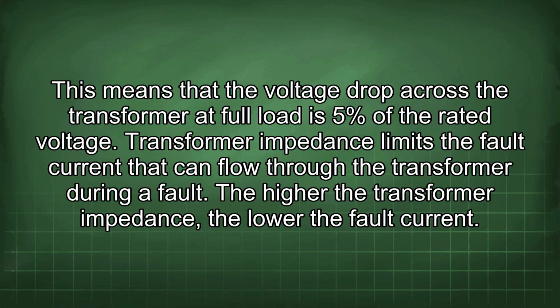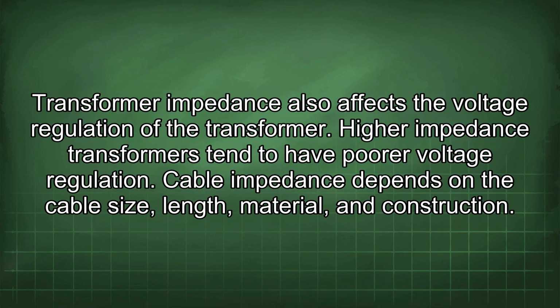Transformer impedance limits the fault current that can flow through the transformer during a fault. The higher the transformer impedance, the lower the fault current. Transformer impedance also affects the voltage regulation of the transformer. Higher impedance transformers tend to have poor voltage regulation.